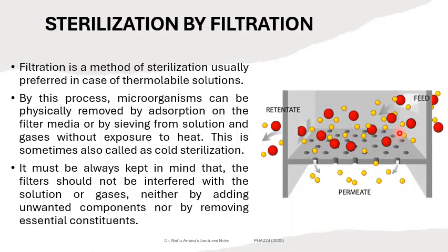This avoids using thermal methods that can have certain deleterious effects on the solution. So this is sometimes also called cold sterilization because it does not involve any heat. It must always be kept in mind that the filters shall not interfere with the solution or gases, neither by adding unwanted components nor by removing essential constituents. So the development of filter media has to be carefully done. We cannot use substances that are active, that have the ability to absorb or leach out their components to contaminate the solution we are processing. So that's what this statement is saying.